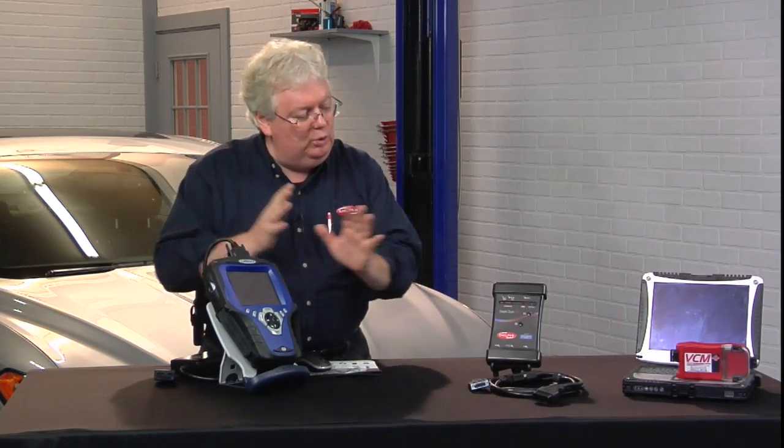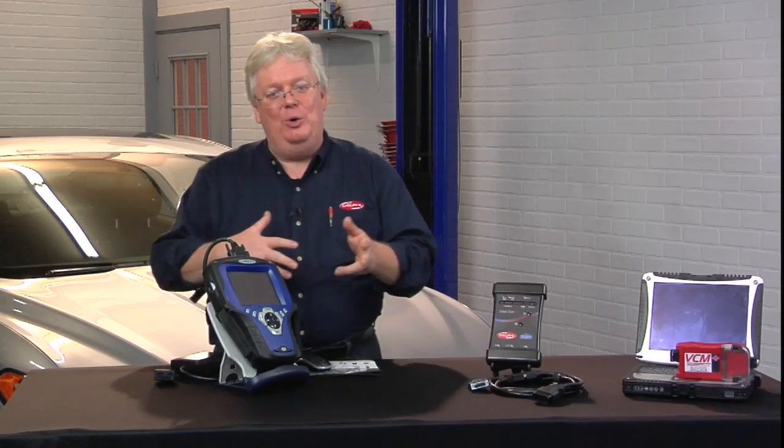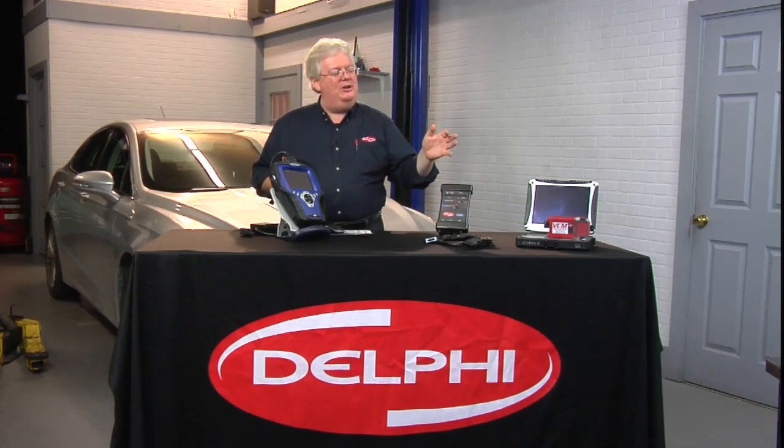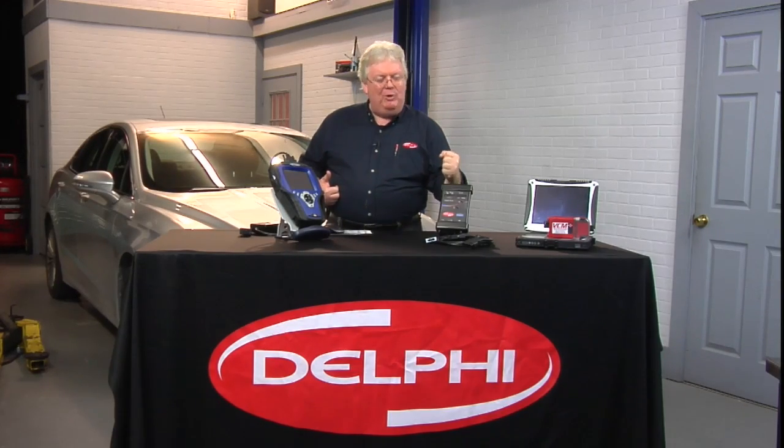I believe some of the other scanners out there, NGS and so forth, some of the Asian scanners did not do mode 6 originally. When they became PC-based scanners, for the most part, is when we started seeing the factory tools adopt what the aftermarket tools have always had, and that is the option to go into mode 6 diagnostics on OBD II. So traditionally, the answer would be false, looking at the older scanners, but if you're looking at IDS, you're looking at TechStream, available on any reflash tool, or even the new MDI for GM, replacement for the Tech 2, they do it, so I can see how we'd have a bit of a controversy and maybe even reverse a scenario.